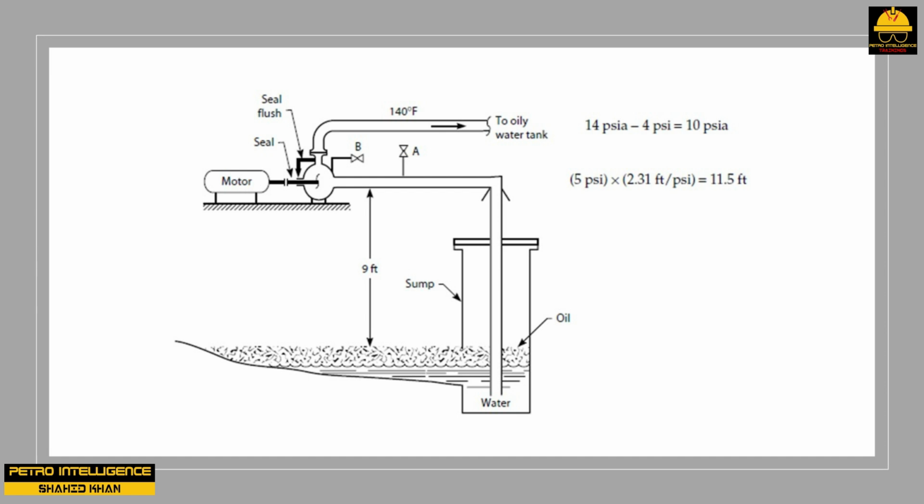A pump that is lifting very cold water, with a very low vapor pressure, through a smooth, low frictional loss suction line, with a very small NPSH requirement, operating at sea level, where atmospheric pressures are high, can lift water to its suction by perhaps 30 feet. The pump shown in picture can lift 1200 GPM of water by only 15 feet. When the water level in the sump drops to 15 feet below the center line of the pump's impeller, the pump will cavitate. Where, then, does the available NPSH to a sump pump really come from?